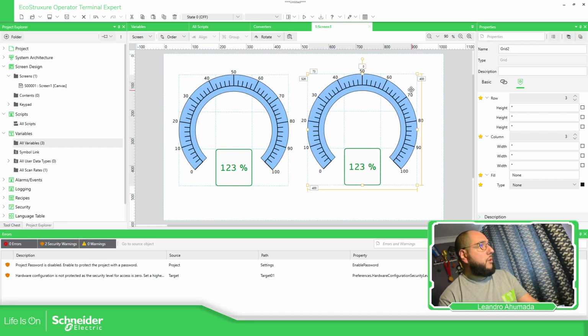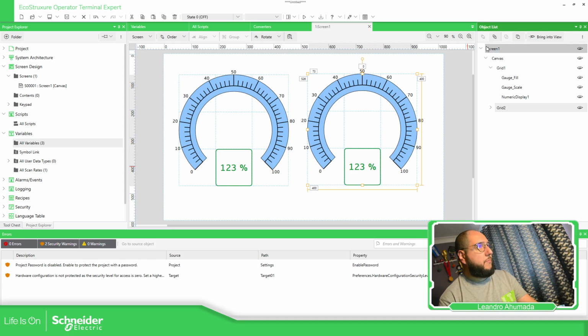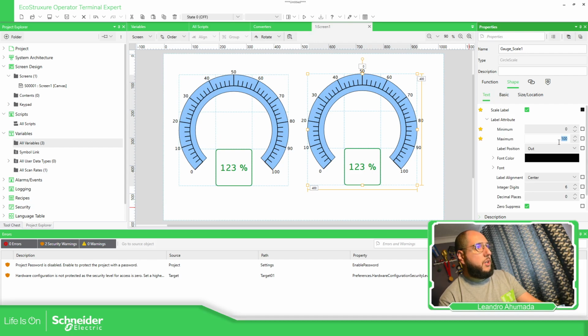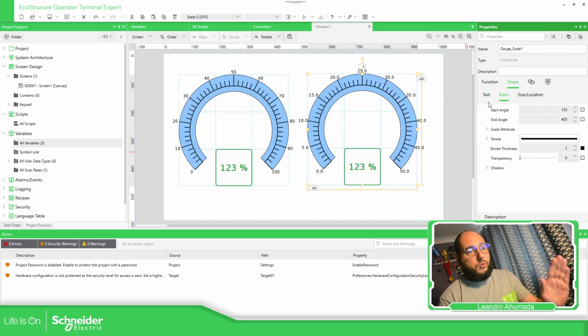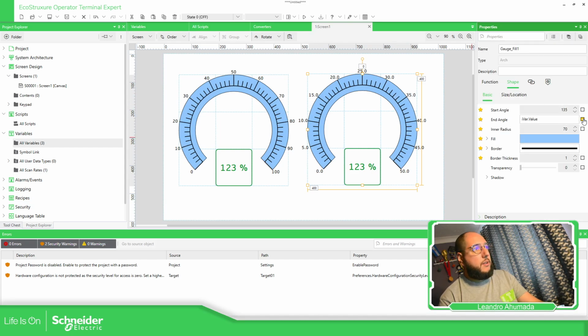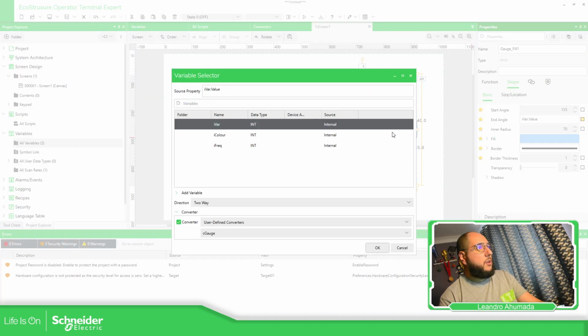Okay. So now what we need to do is to change the grid to scale. So it's gonna be function text. It's gonna be 0. Okay. Integer is gonna be 2 and 1 decimal point. Okay. The other thing is going to be the same. You don't need to touch this. If we go to the objects list again and gauge, now the properties is going to be a different variable or a different converter.